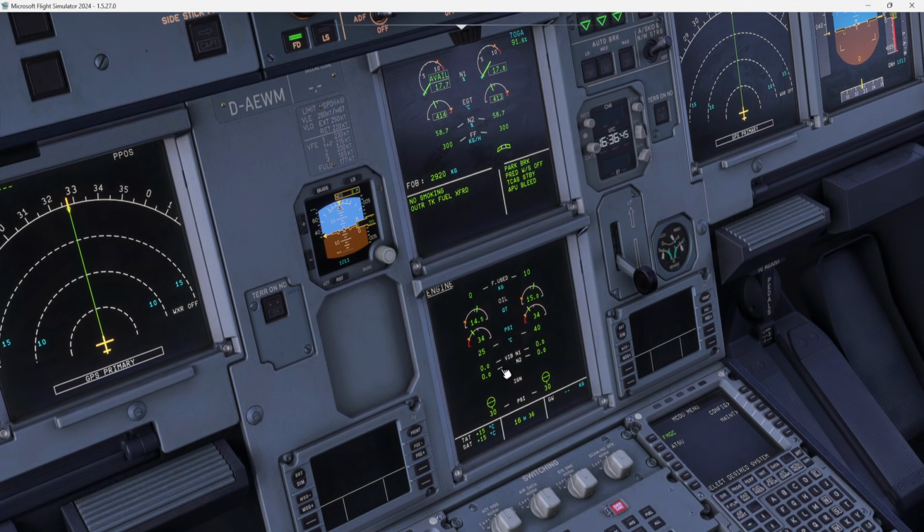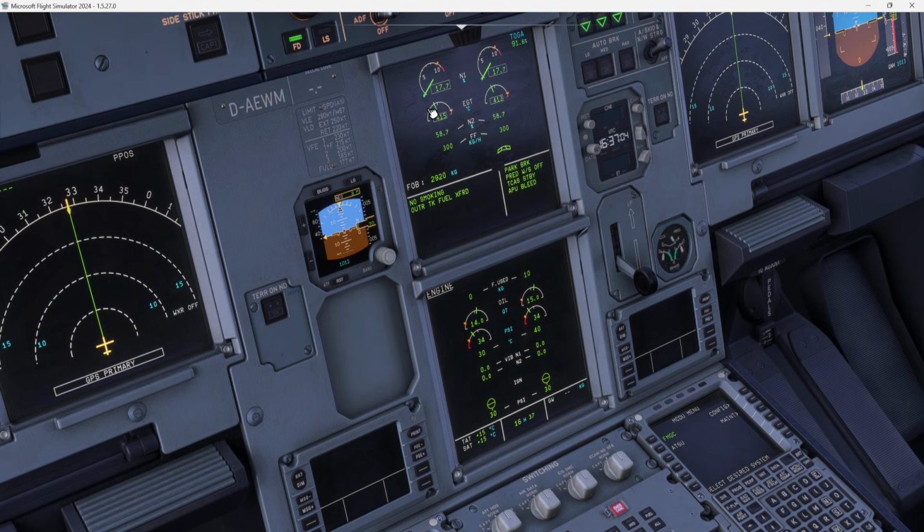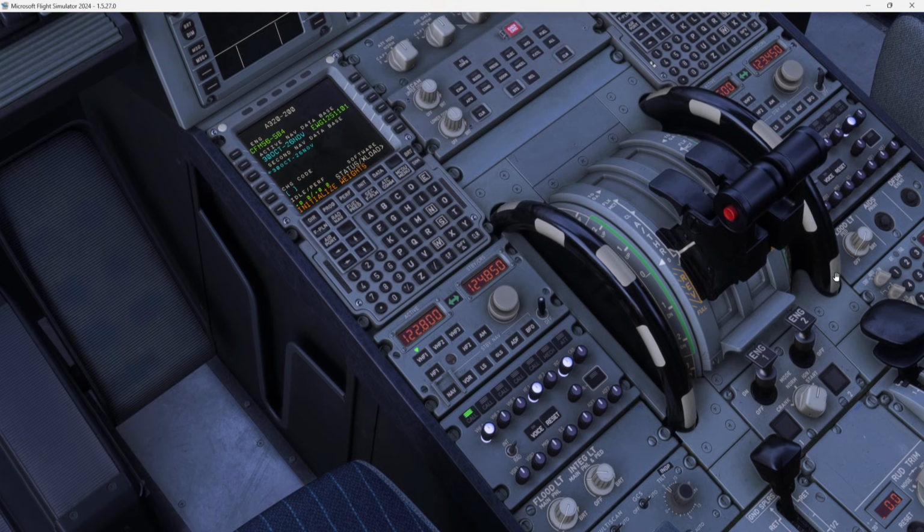So now look what's going to happen here. The FADEC is going to say, okay, everything is good. Look here, the temperature of the oil is going to rise. Okay, this is going to rise until 40, and engine vibration looks good. Let's see. Okay, this one disappears, and we have, my friend, good startup.